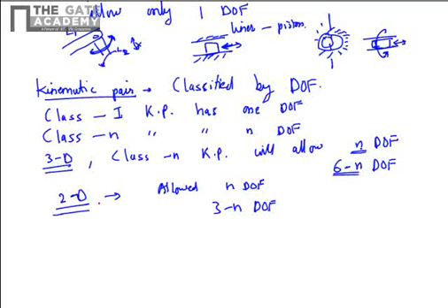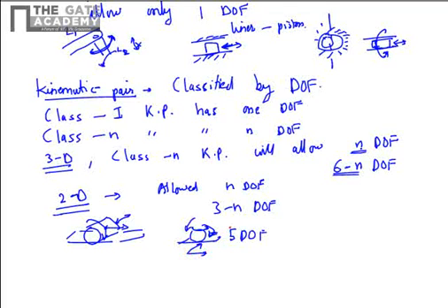We will just note here that lower classes of kinematic pair are more constraining, and we have the pair moving in a more predetermined fashion. If you go for higher kinematic pairs, you can see examples of a cylinder resting on a surface or a ball resting on a surface. It has translation along this direction and the other direction. It also has a rotational degree of freedom. A spherical ball staying on the ground has 5 degrees of freedom. It can rotate about any axis, 3 degrees of freedom, and it can translate along the x and y axes.